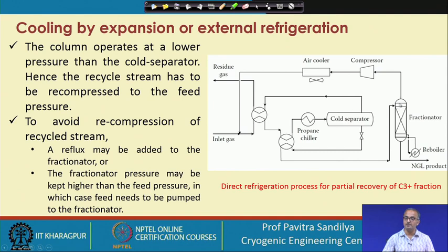Here you can see that we are not doing any kind of reflux, as we learnt earlier that reflux helps in increasing the separation of the heavier components from the vapor. That thing we are not doing here, so that is why we have to recompress it, and this may be avoided if we put some reflux over this fractionator.